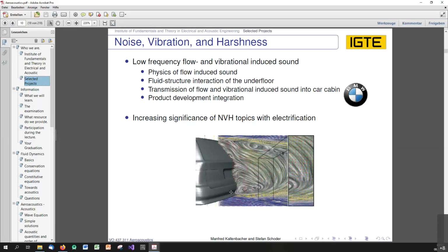So in this sense, if the physics matches in the low frequency range, it's definitely valid. I would not recommend using finite element in the 15 kilohertz range or so, because usually you would like to discretize a wavelength with about 20 elements if they're linear.